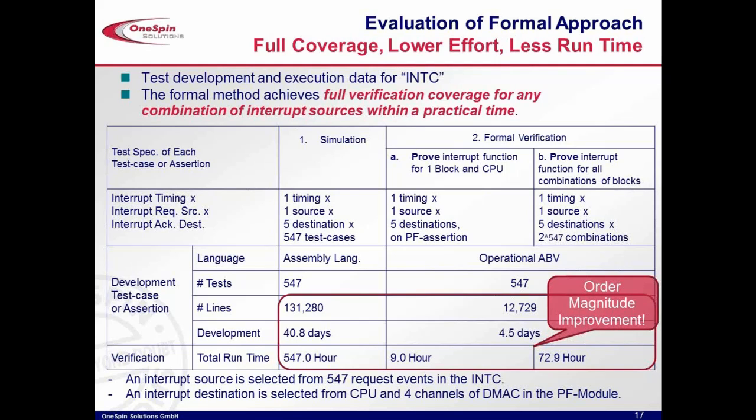Simone Borri, Abilis Systems. So Sergio, it seems that you highlighted at the beginning of your presentation that today your focus for formal verification engines is more to provide out-of-the-box solutions to some specific problems. Does this mean that the good old way of using the formal engine to verify a certain property, where you write the property, is not really the focus today? And has there been any improvement in the way the tool can handle this kind of situation where you want to prove a certain design property? What is the kind of design size and sequential depth which can be handled by the tool today?